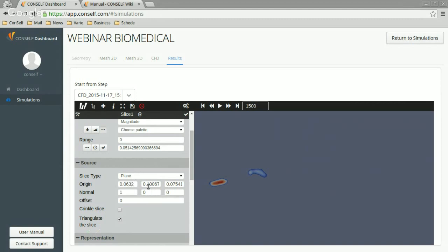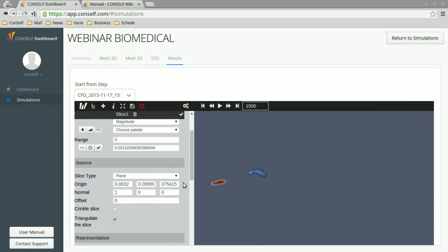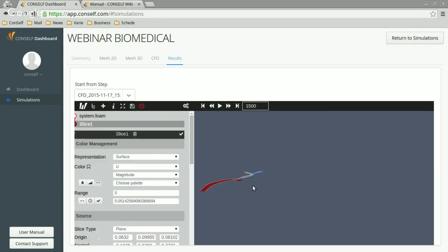The Y is 0.09959. Z is 0.08102, while the normal is minus 0.1036, 0.8269, and 0.7721. Okay, well, now I can just click apply, and you will see our slice right here.